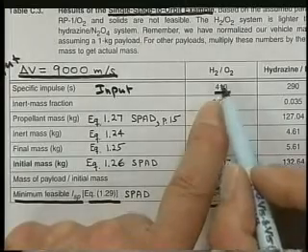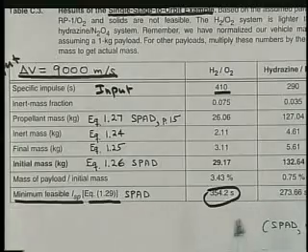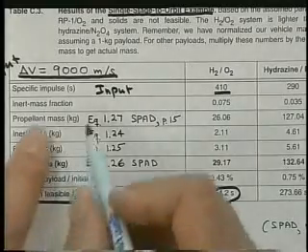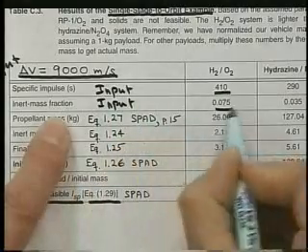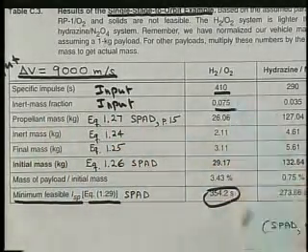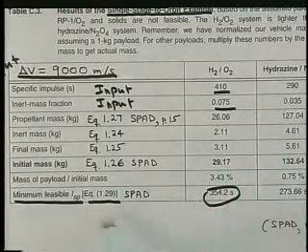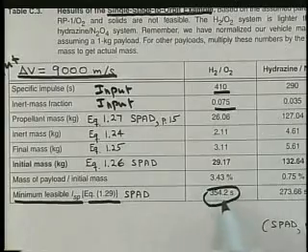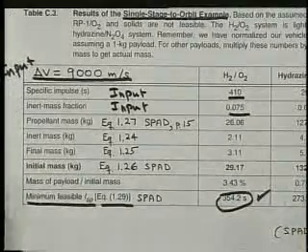Therefore, hydrogen LOX with the mass fraction of 0.09, which we also need as an input to do the calculation, is a feasible case. 410 is bigger than the minimum ISP that we calculated in the feasibility equation. So 410 being bigger means this checks out, and we can continue with our calculations.